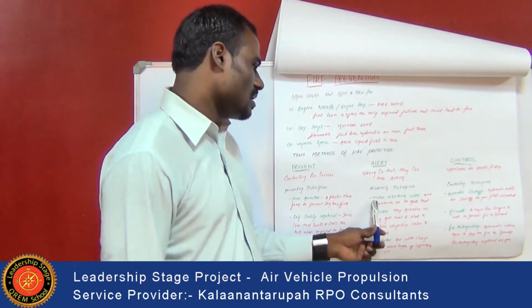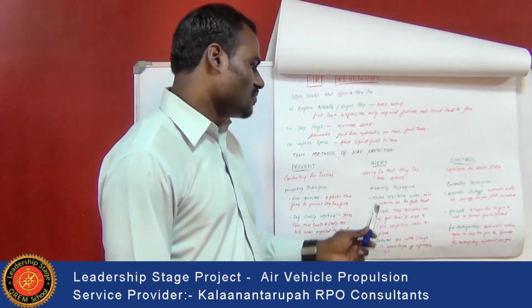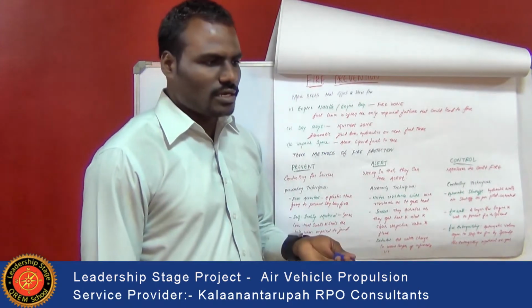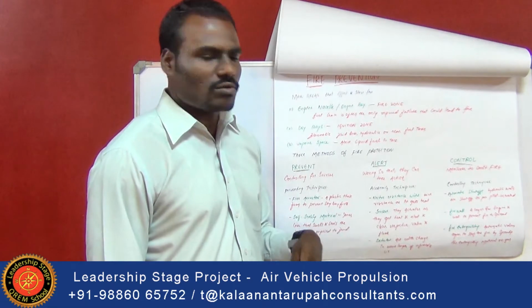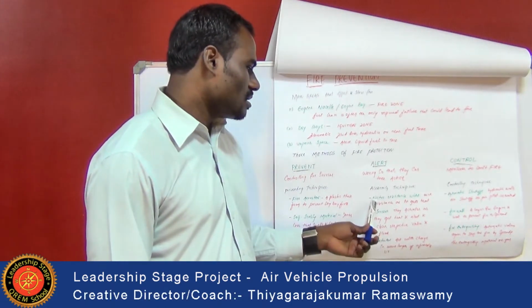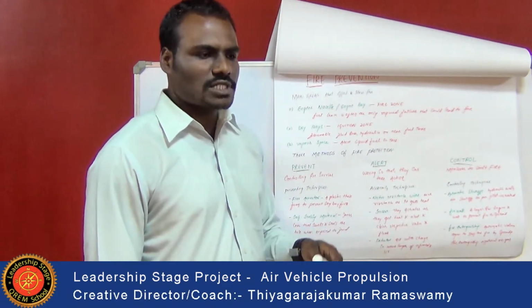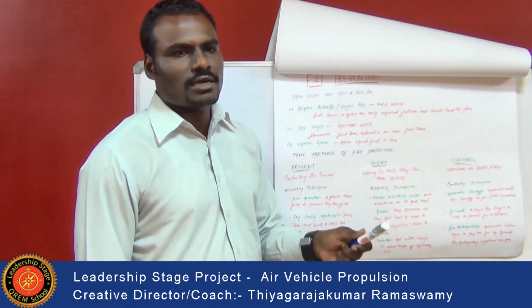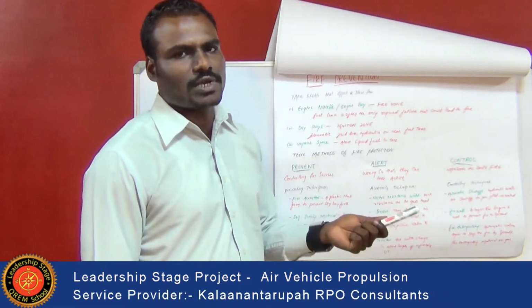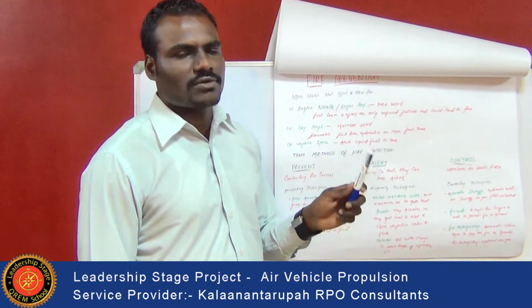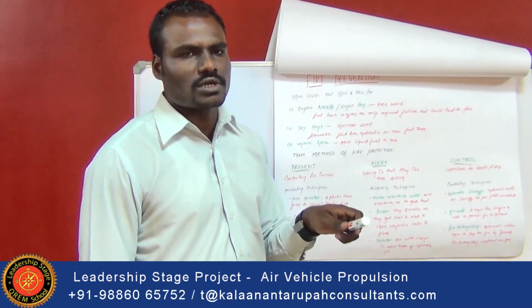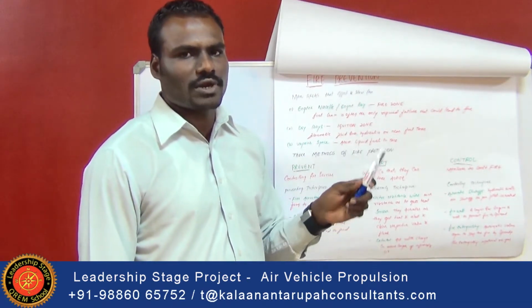The first one is the electric resistant wire, which finds out the heat that has been created, and this resistor wire sends a message to the cockpit, which gets a command to stop the fuel control from the cockpit.